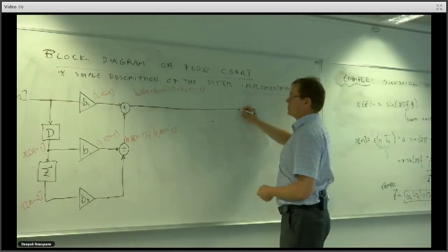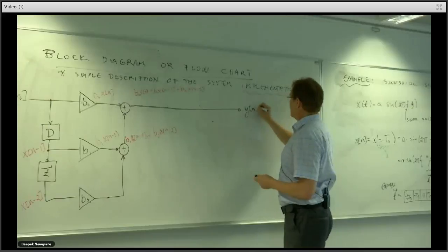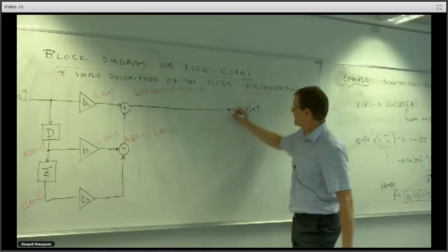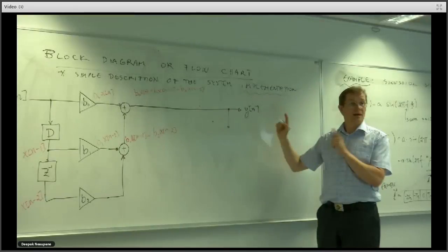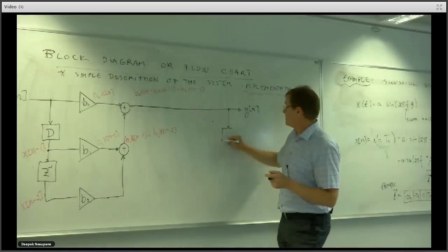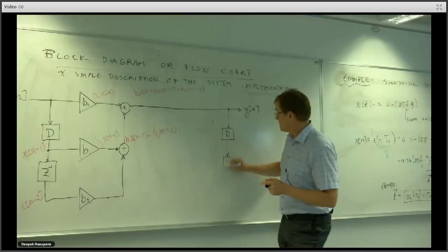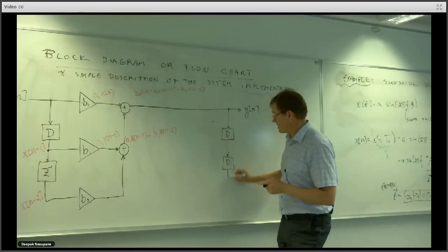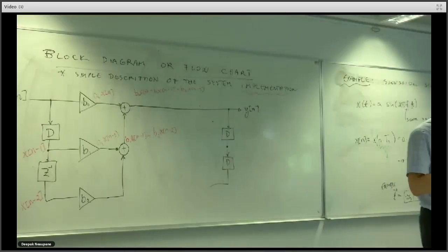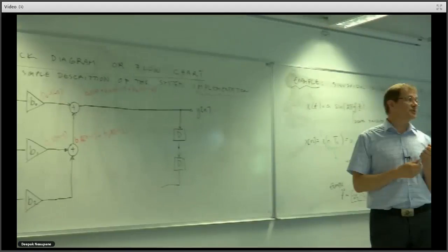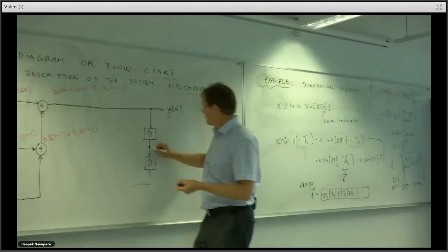But output yn, if you need feedback, you cannot directly use that one since you are calculating it, the system is calculating it, but you have the previous value or previous values, okay. Delay, maybe 2 previous values like that one. And on amplifiers, when you're using negative feedback, you will just put a part of the signal back to the input to have the gain. Same thing here.